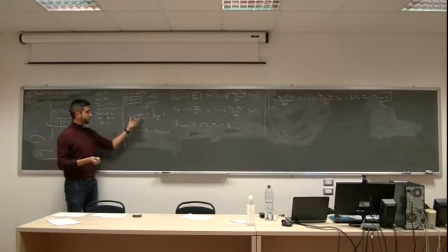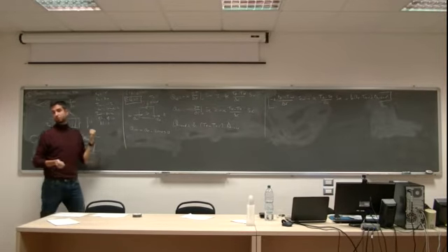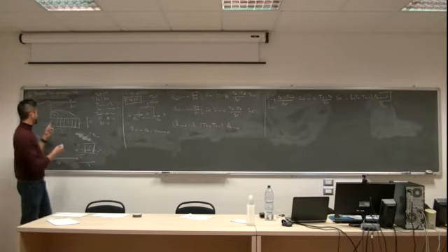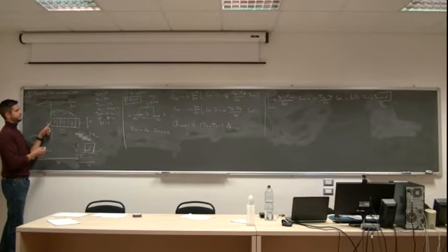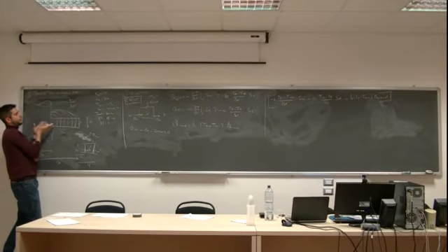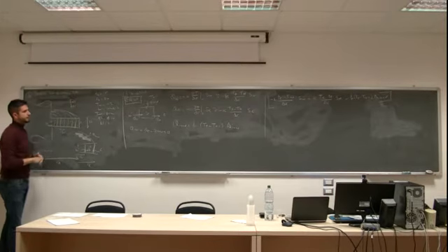It might happen that you don't know the direction of the heat flow. In this case, we know, because I put the numbers here. And because this is 70 and this is 25, we assume that the heat flow will go this direction and towards the outside.